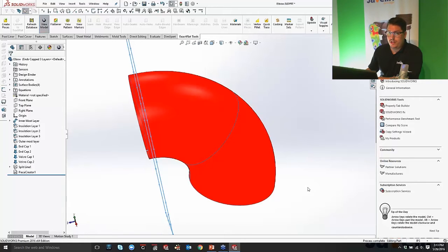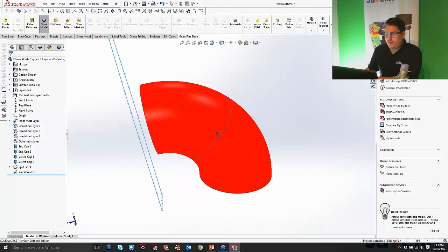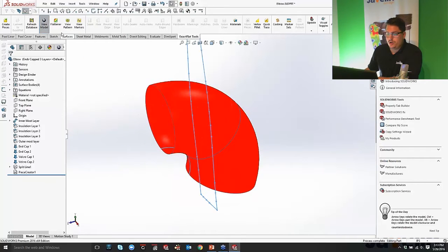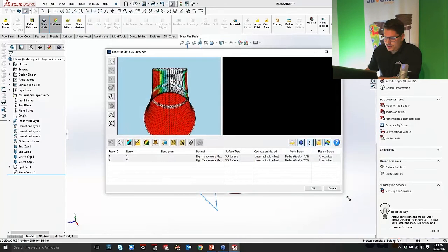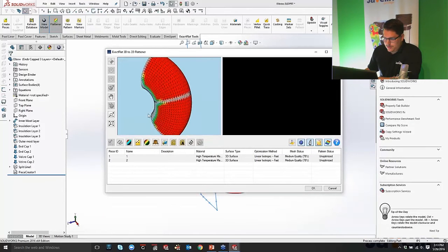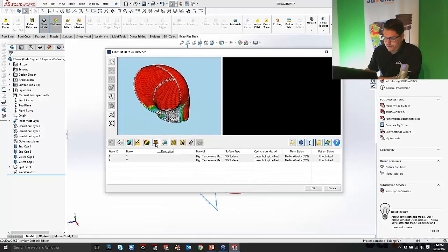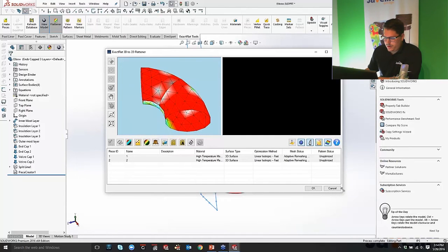So this is really good because we generally don't just have one layer. We've got multiple materials inside of our models, and each material can have its own color to make sure that we're mapping it correctly to the right pieces, and it gives you that instant visual feedback. Okay? So now that we've applied our material, we can go right into the flattening process. So we can go into our flattener, and we get our 3D view, and we can just give it a quick remesh there.